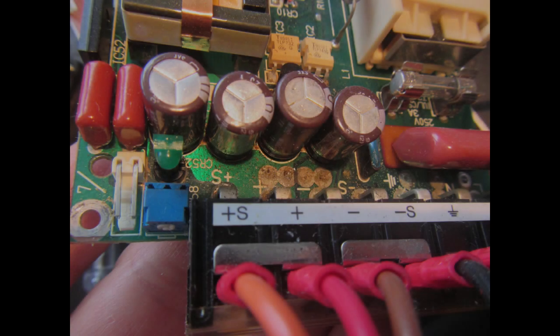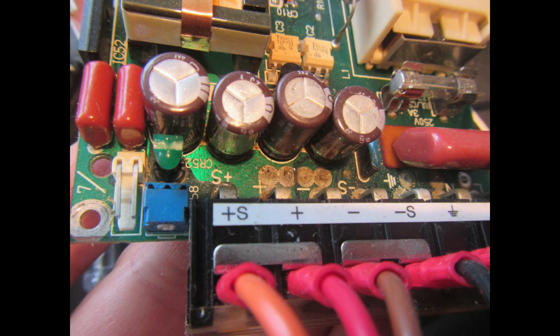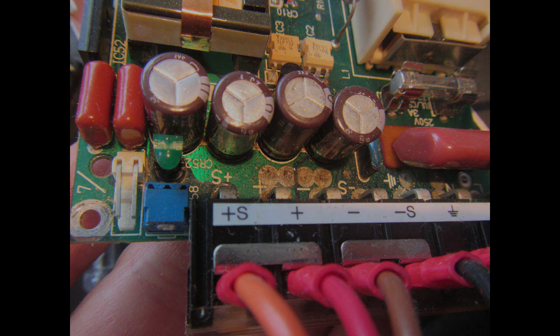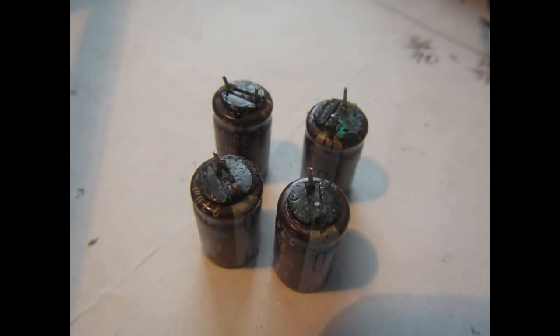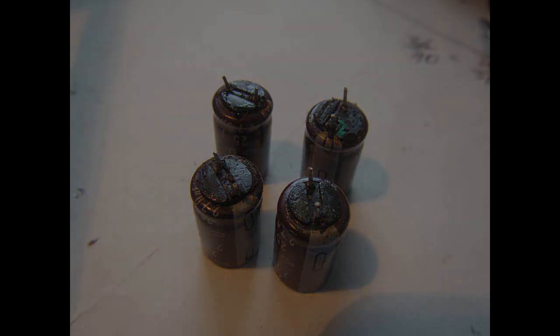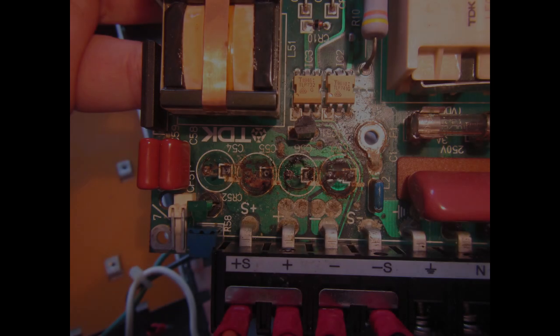Here the issue is evident from the filthy and smelly substance leaking from the 4 electrolytic capacitors. The highly corrosive liquid also arrived to the pins of those other components. The first thing to do is, of course, remove the bad capacitors, and for the record they are Nippon Chemicon branded. Then the PCB must be carefully cleaned.